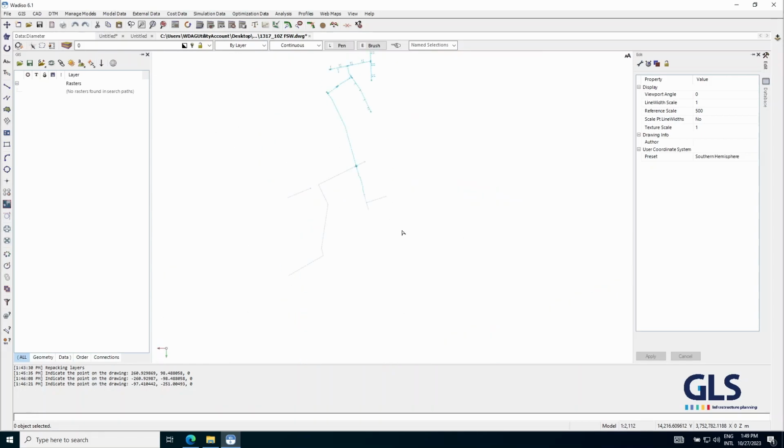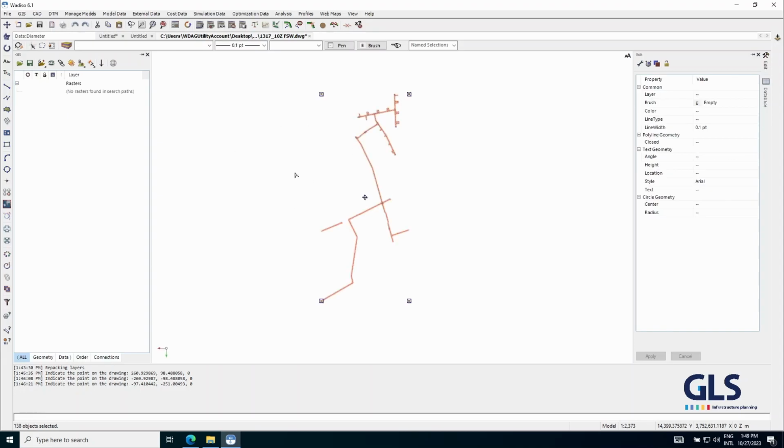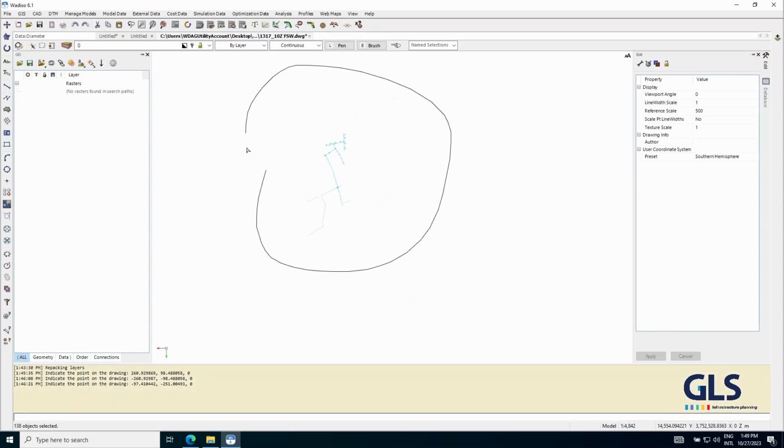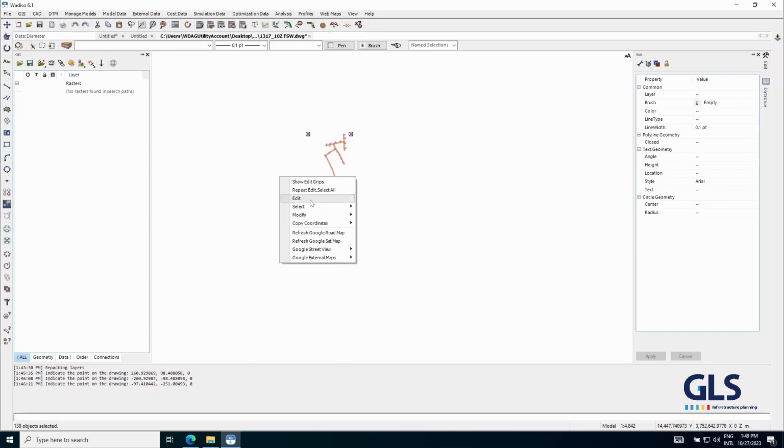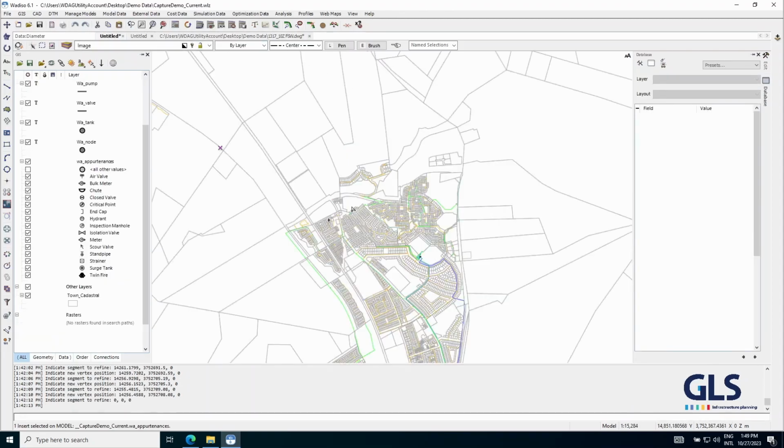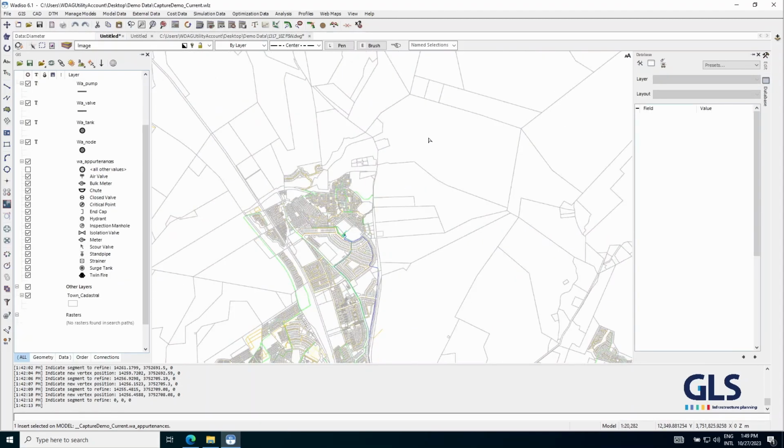So now I have all my CAD layers, the correct orientation that I actually want to consider on this drawing. Only these are visible. What I can do now is on this space, hit Control A, which will select everything. Or if you really want to, you can make a selection like that. So Control A, right click, edit, copy, move to my original drawing world space, and over here I can say